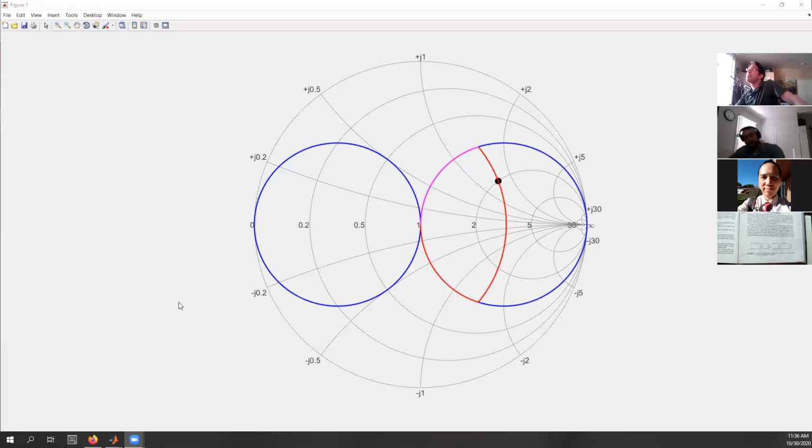Yeah. The follow-on to that is, why is the stub now being used? Because we're using a stub to put an effective capacitance or inductance on the transmission line versus just slapping an inductor on it. So when we get to the stubs, we'll discuss why the stubs outperform. Well, it's very easy to just machine in a length of transmission line on a little printed circuit board, right?